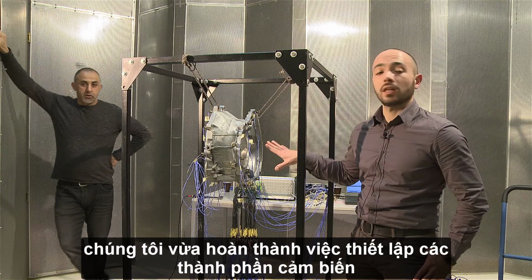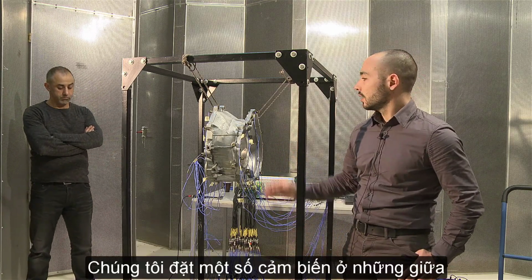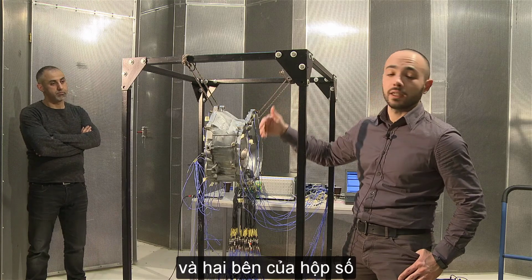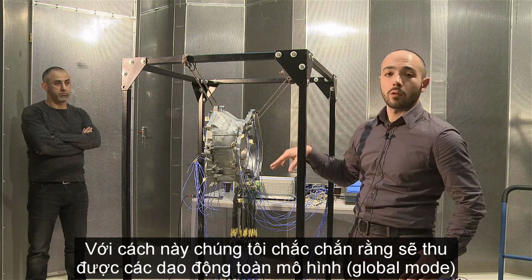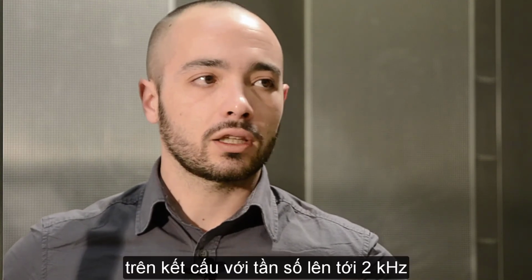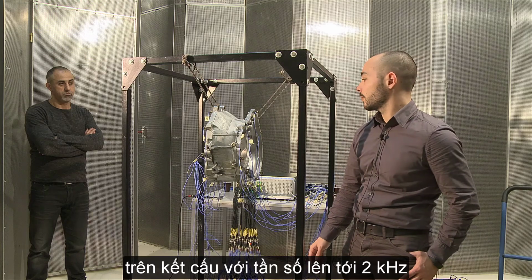So we just finished now instrumenting the component that we want to test. We place several triax accelerometers on both planes of the gearbox in a way that we are sure we will be able to acquire the global modes of the structure up to about 2 kHz of frequency.